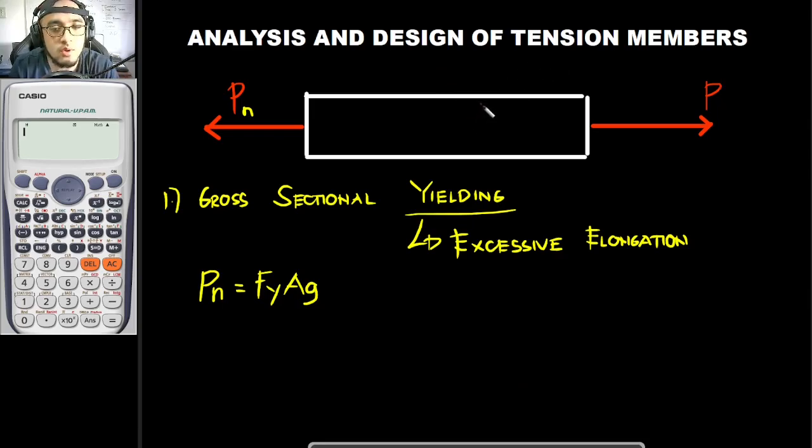Of course, we don't want that to happen. That's why in steel design, AISC has accepted two major design methods. The design methods recognized by AISC and NSCP are LRFD and ASD. These are two of the major design methods recognized in steel design. LRFD is the load resistance factor design, and ASD is the allowable stress design, or the allowable strength design.